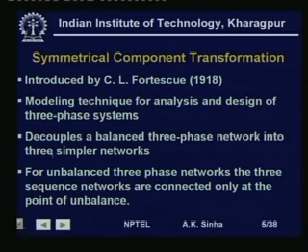Therefore, as we have seen, the symmetrical components decouple a balanced three-phase network. So, for all these components you are going to get decoupled sequence networks. Only at the point of fault or unbalance there is going to be a coupling between these three sequence networks.